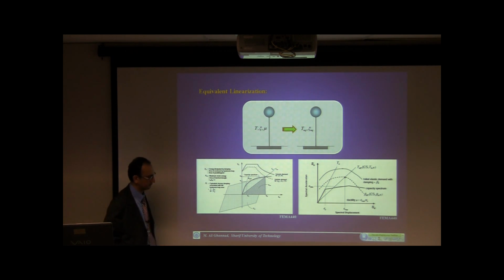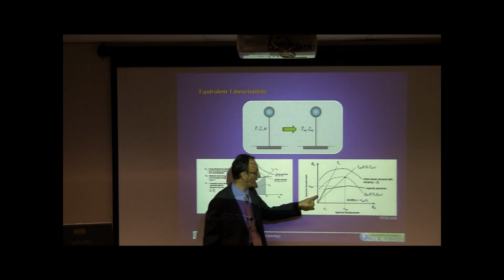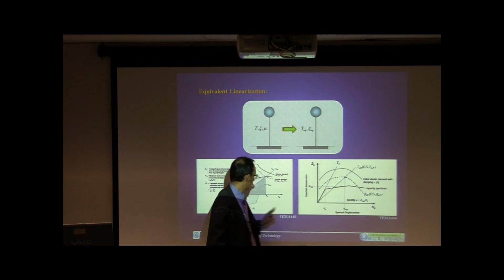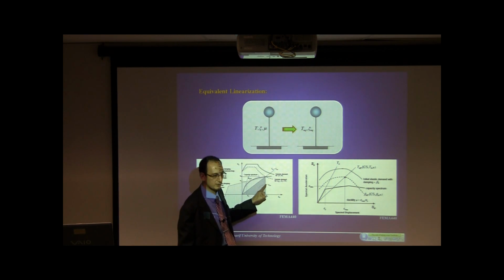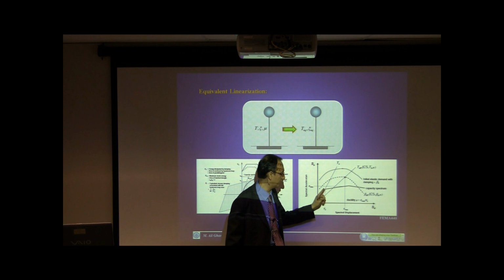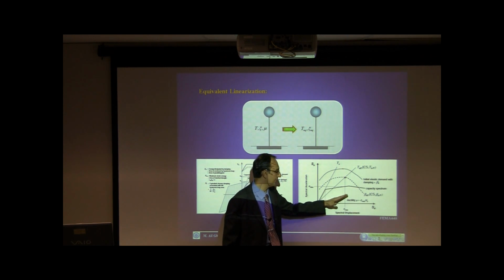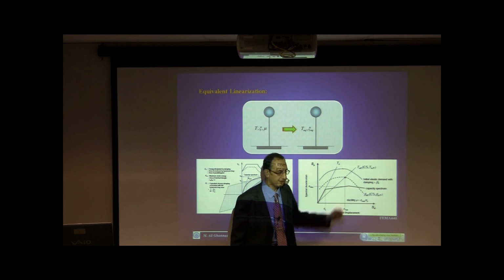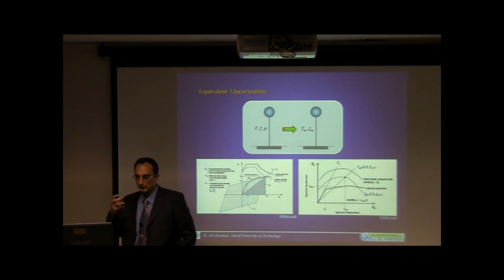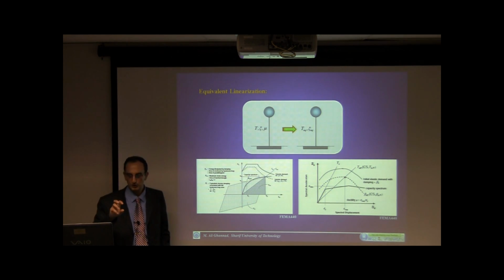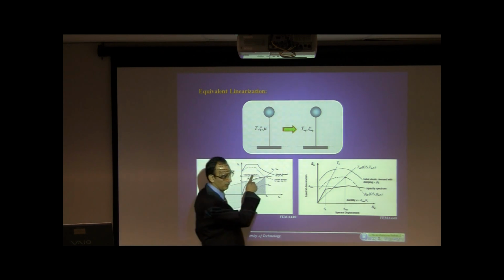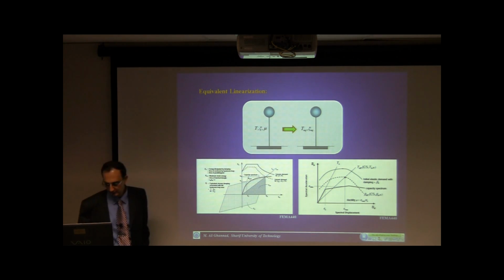And after that, they come with another idea, but instead of using the secant stiffness, it's better to use an effective stiffness, which is something between the initial stiffness and secant stiffness, and combine this effective period with an effective damping ratio to get the response.